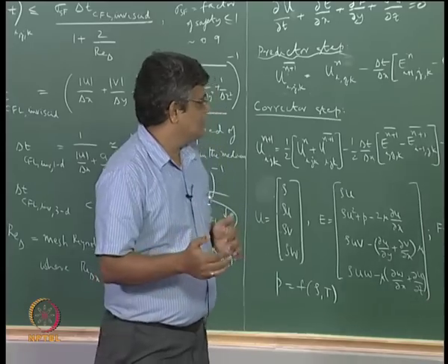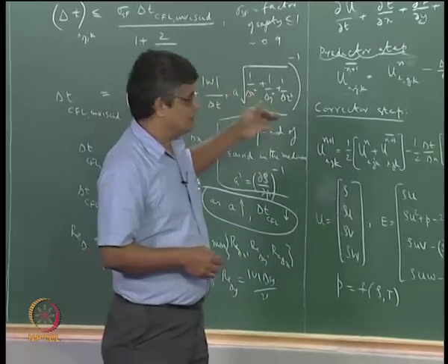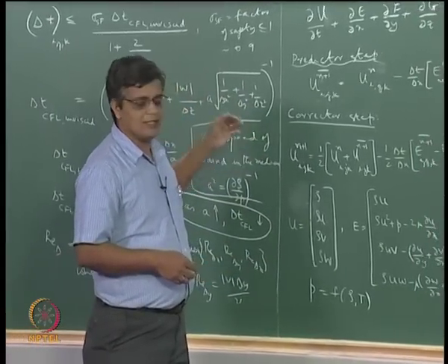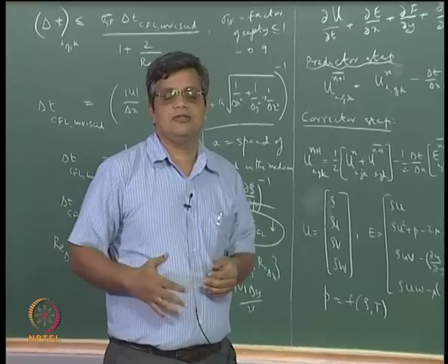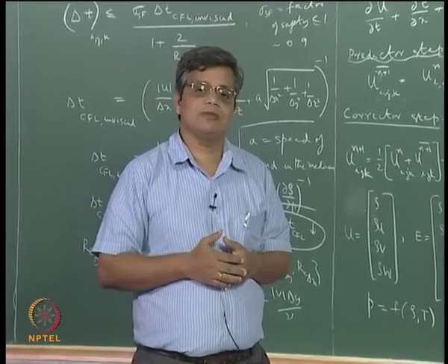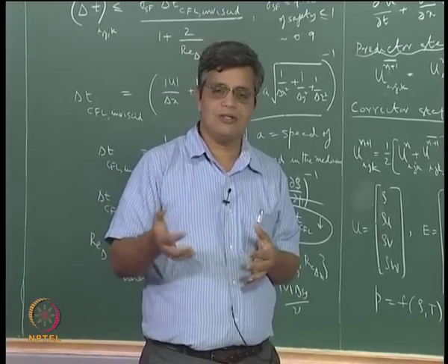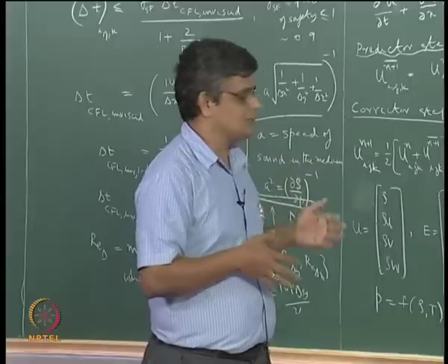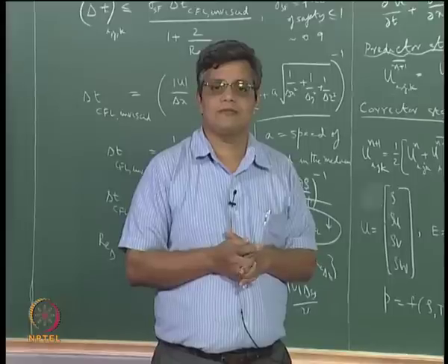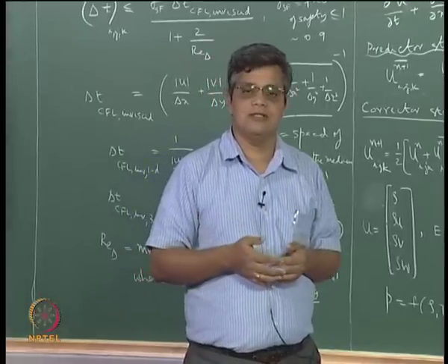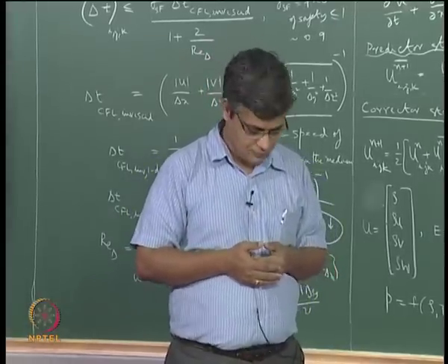Although this MacCormack method is quite useful and has been applied for the solution of the coupled equations, it is not readily extendable to fully incompressible flow calculations, because the corresponding time step required will become impractical. So we need to find new methods, new ways of doing this.